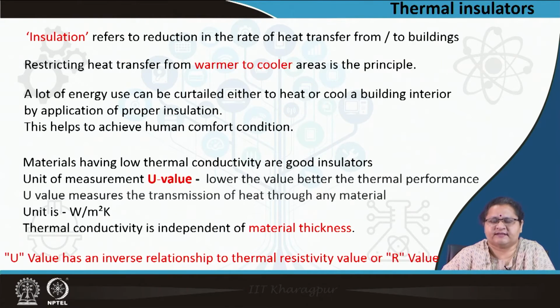U value measures the transmission of heat through any material, and we will look into materials which have low U value, that means higher resistivity value or higher R value. We also need to remember material thickness has a role in the rate of thermal conductance or resistance. So, thickness of material is also important.